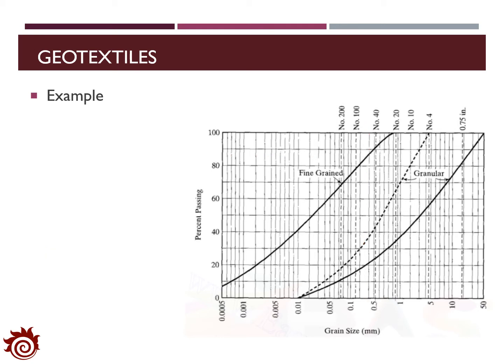And then we can go to check the AOS requirement for the granular materials in this figure. From the definition of the retention criterion for granular materials, we see that we don't need to think about the portion of the material which cannot pass through the number 4 sieve. So we will only keep the part which can pass through the number 4 sieve and adjust the grain size distribution to the dashed line here.